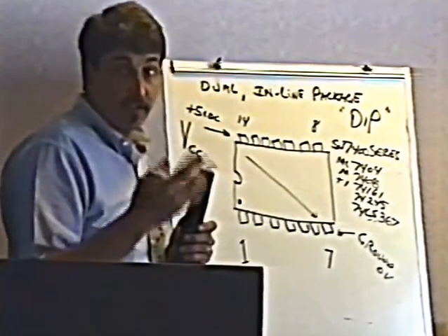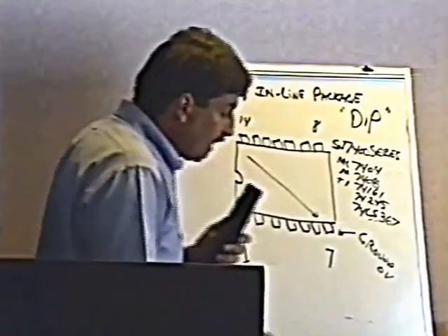And with the power turned on, I just go right across those chips. Now, when you do this, really important, it's very easy to slip with your meter lead. So you want to be careful because the power is turned on now. When you put your meter probe on this thing, don't try to put your meter probe right on the top of the pin because, bam, you can slip and short these two together. Put it here instead, in between the pin and the body of the chip, like that.